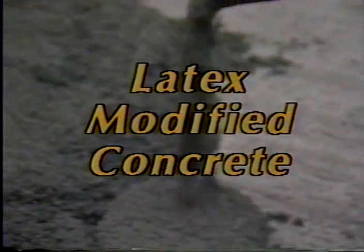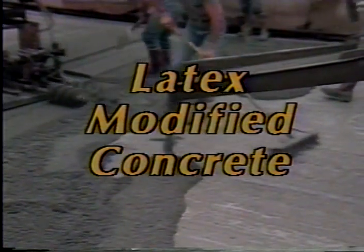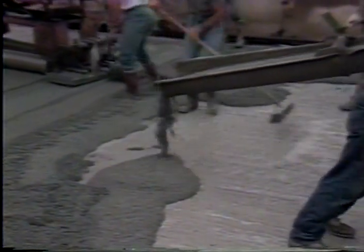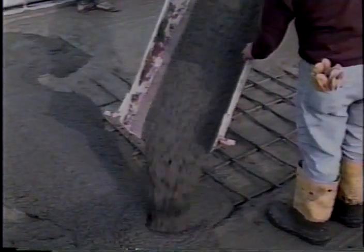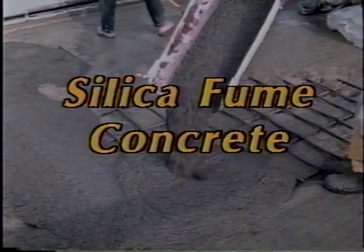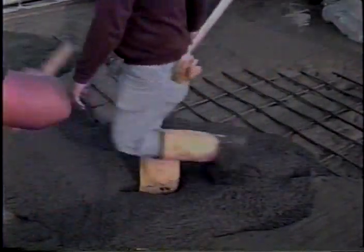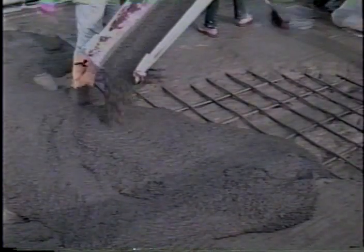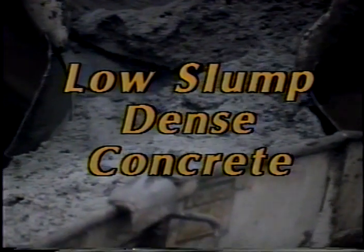One such special mix is latex modified concrete. When used with Type 3 cement, the overlay can be open to traffic within 24 hours. Another special mix used for bridge deck overlays is silica fume concrete. This material has low permeability and therefore greatly reduces chloride infiltration. Yet another special mix is low slump dense concrete. Thousands of this type of overlay have been constructed.